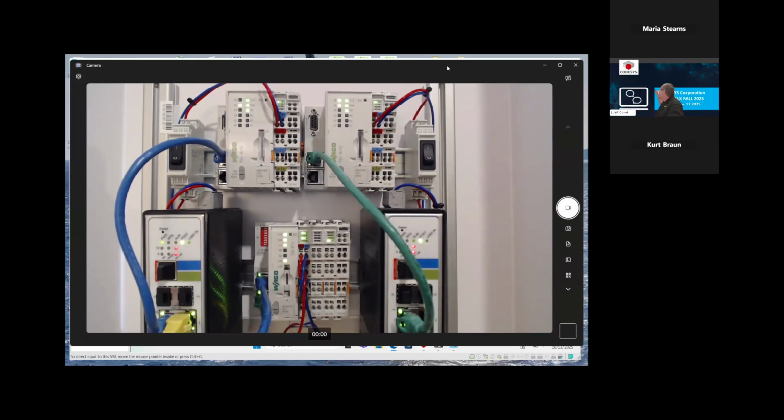And I'm going to go turn off. So this one's the primary master now. This is secondary. When I turn him off, the lights are still functioning as they were before. There's no interruption. Again, a yellow light at the top indicating that he's in standalone, that he is not seeing the other master, but the process continues without any interruption.